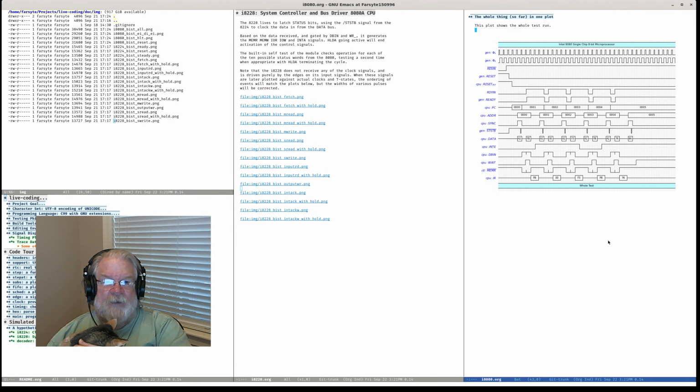I was trying to find the actual UART chip that we used to use at Sun. I did serial drivers for Sun for a number of years, and I remember that the chip was easy to use. It had a nice 16-byte silo in it where you could load up the silo and data would flow out, or you get an interrupt and maybe 3 or 4 characters that come in before you service the silo. So we could handle some very high baud rates as long as we got back in time to catch it before the silo emptied or filled.